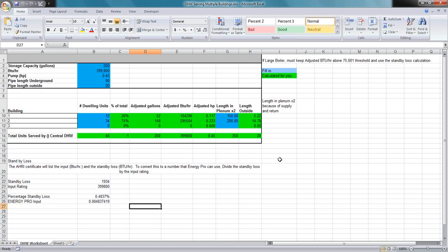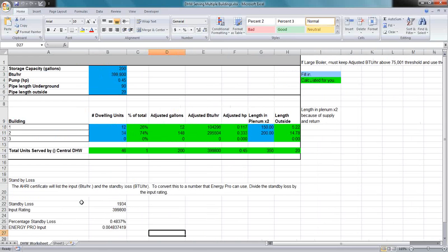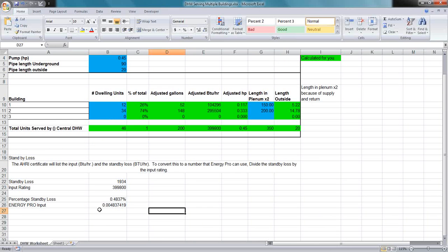It's a convoluted topic, and it's hard to explain without numbers to look at in front of us. But the correct standby loss number is usually on the order of 0.00-something for the water heating systems we're working on. Kyle's showing you there what his number was. So if you've got a number in that range, it's probably accurate. Feel free to send it over to us for review.